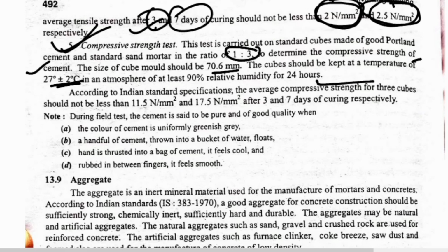According to Indian Standard specification, the average compressive strength for three cubes should not be less than 11.5 Newton per mm square and 17.5 Newton per mm square after 3 and 7 days of curing respectively.